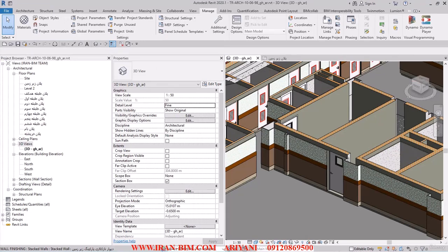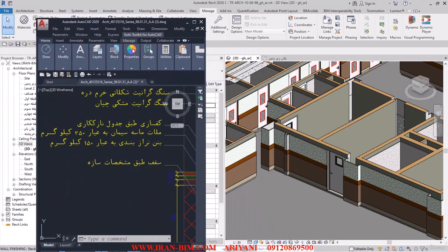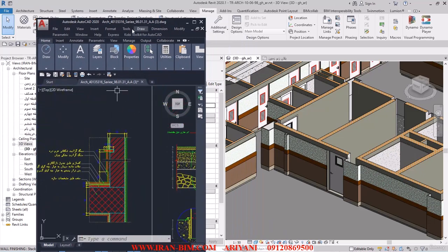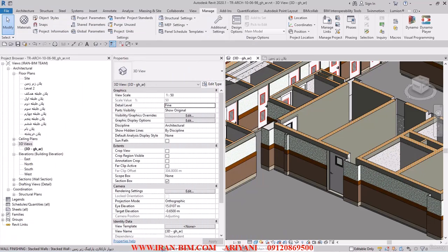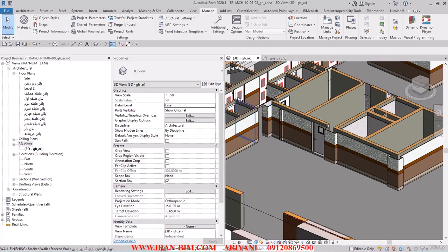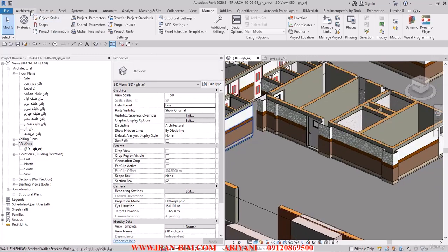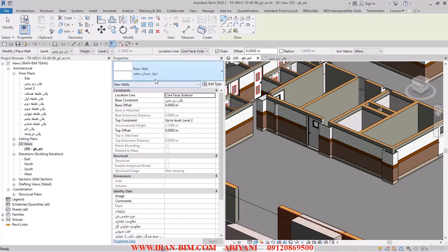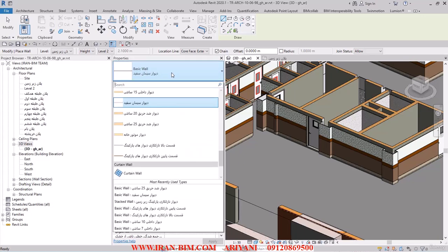Let me just go back to the CAD file to show you this wall. This wall is from the lobby part, and we're going to model it now. Now, I can do all of this part with the same type of wall. And in order to do so, I can go to this part here, because the upper and the lower section of the wall is pretty much the same. So we go to the Architecture tab, and then in here we select the wall tool. Let me just do that, and after we've done that, we'll just make one here as a sample, and there you go.